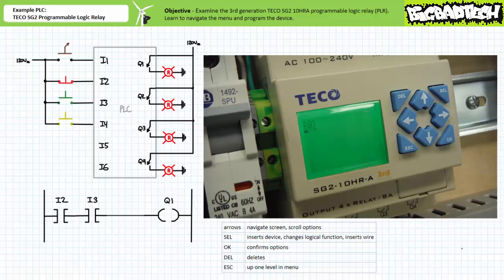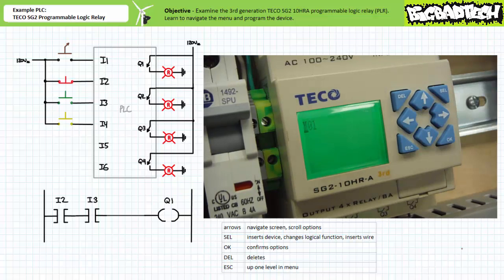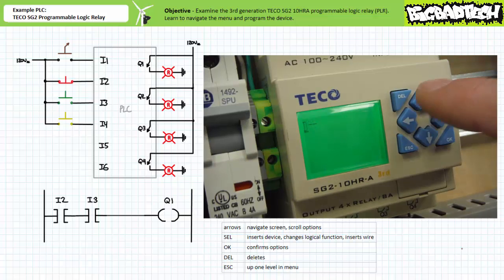If I wanted to draw a wire, I'd have to press Select again. If I press Select again, I'd be back to a blank device, and if I press Select again, I'd be back to the original terminal input entry of input 1. The up and down arrows, in contrast, change contact function: X, Z, Q, Y, M, N, D, T, C, R, G, and back to I. We'll examine these other entries in later lectures.